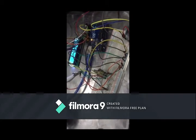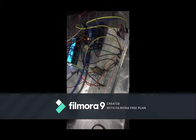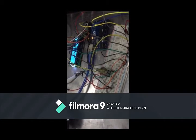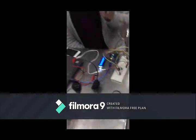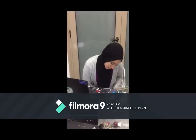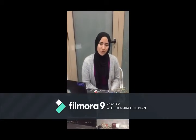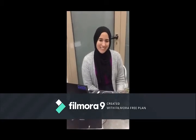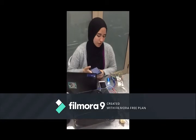and we connected the VDD with the 5 volt from the Arduino, and we connected the V0 pin of the LCD to the middle pin of the potentiometer, which adjusts the contrast of the LCD. We also connected the read and write pin of the LCD to the common ground of our project. And that's all about the connections of the LCD. Thank you. We connected an Android device to the MIT app.